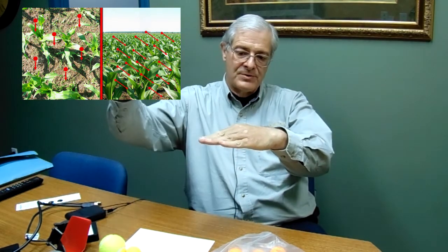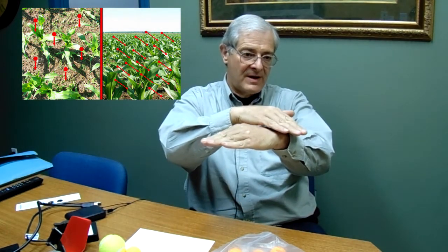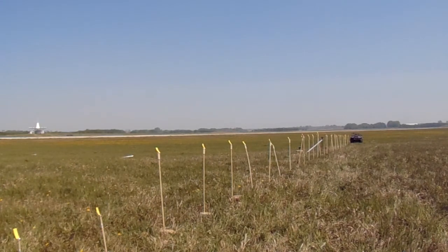So for that reason, especially when you're using relatively small droplets, I don't like the idea of using only a horizontal card, because the small droplets might skate over it obliquely and not impact. On the other hand, if you used a purely vertical card, the big droplets might pass it. So it's a good idea to use an angled card, as we've been doing in our tests here, typically at 45 degrees. So you have a collecting surface that works both for the droplets moving horizontally and those that are moving vertically.